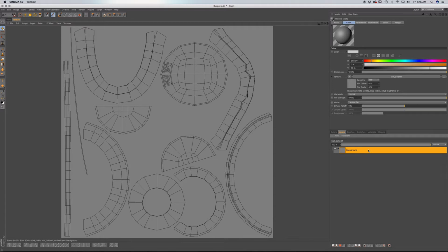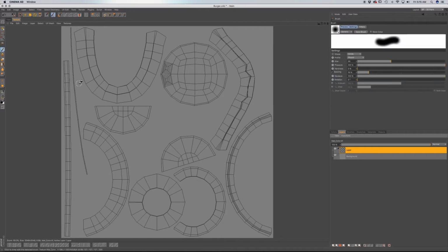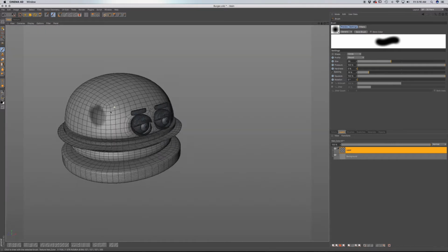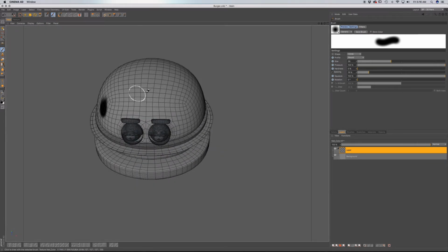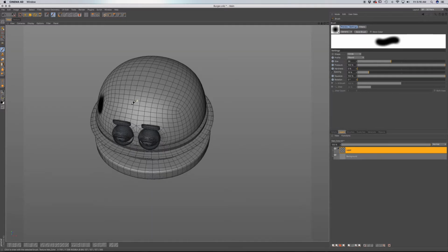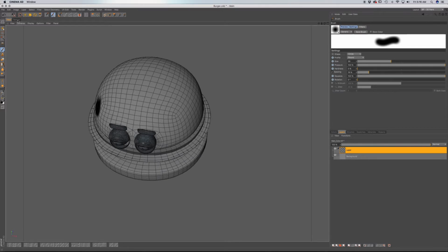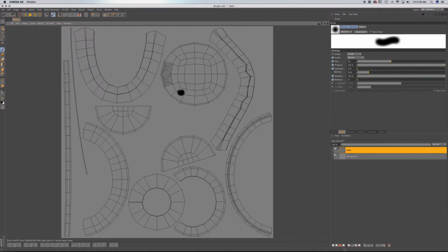You can go to layers and then choose a new layer. And this is what I do, and what helps me a little bit is if you just take your brush and with some kind of color, paint in this area and then go to your 3D view, you can see your little mark here, and that's where you know what mesh corresponds to what you're going to be applying your paint, or in this case an image, to. So I'm going to go back to texture and you can simply just delete this layer. You now know that this is your bun image.